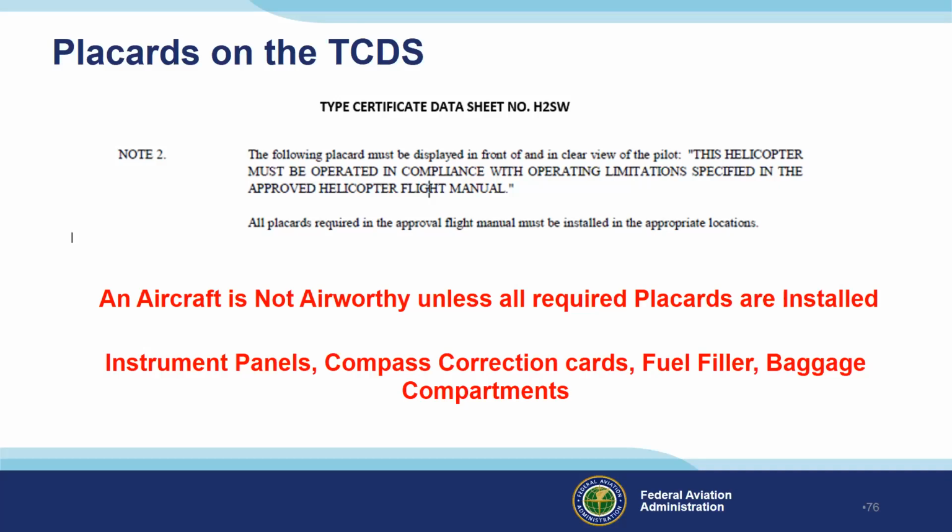And probably one of the most common things an FAA inspector will find on a ramp inspection are placards that aren't there, or you can't even read them. Some examples would be the compass correction cards, the fuel filler placards on the top of the wing. A lot of times they get damaged and the aircraft gets painted and they don't put the placard back on. The baggage compartments probably have a placard of the maximum weight, and that's very important. So make sure the placards are there.